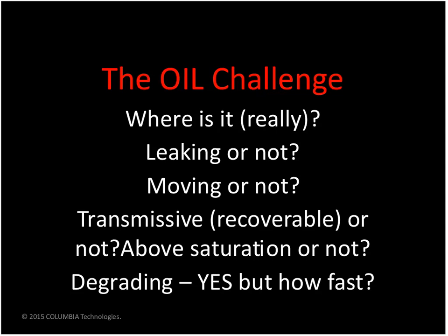Have we stopped or secured or turned off or controlled any existing leakage, sources of oil, sources of contamination, sources of pressure, when we get into the discussion about pore pressures and things of that sort? Now that we've done that, has the oil reached equilibrium, or is it still moving through the subsurface? In other words, is it leaving our site or our area of concern or our controlled area, or has it pretty much reached equilibrium with the subsurface formation and it's not, using ITRC's term, moving?